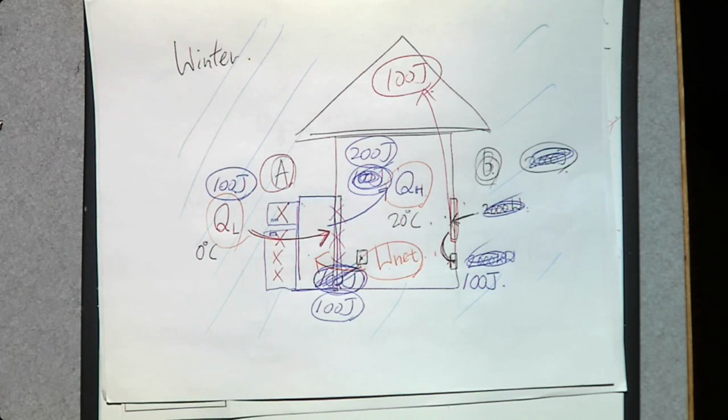So you're only spending 100 joules, but you are actually delivering more than 100 into the house. So the efficiency is always greater than 100%, because even if the refrigerator is pretty old and cannot absorb as much as before, maybe 1 joule of heat transferred into the house, you still have 100 joules of heat from the electricity, and you have this one on top of it. So it is always higher efficiency than 100%. Interesting, right?